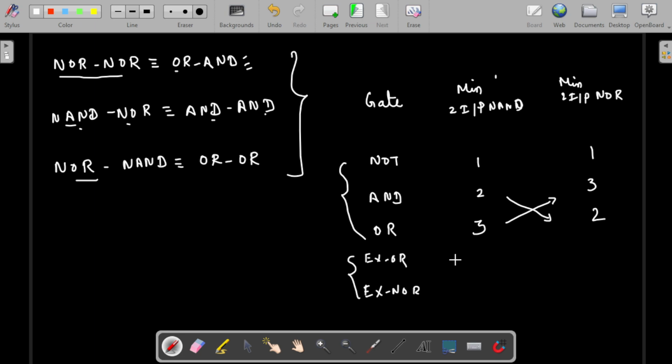So here, how many two input NAND gates are required to build OR gate is 4, and 5 two input NAND gates are required to build NOR. So if we exchange this one, then this will be 5 and 4. Okay, so thing is that 1, 2, 3, 4, and exchange individually. So you have to remember this logic: NAND, NOR, XOR and XNOR. So that is very important.